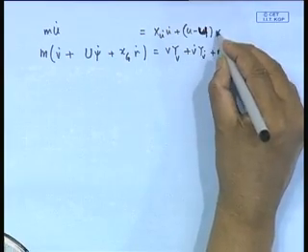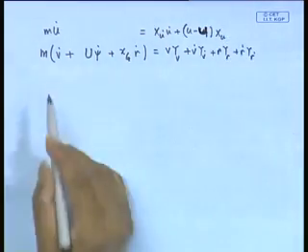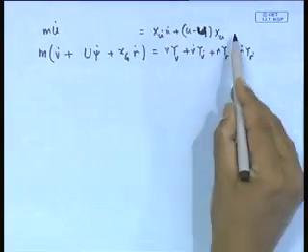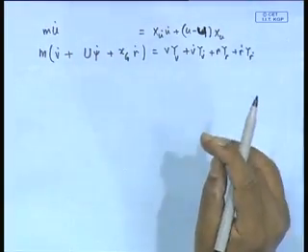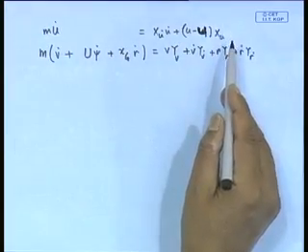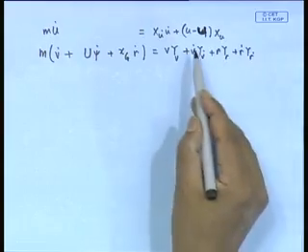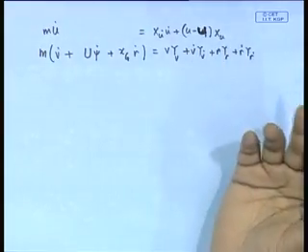What I mean, in the x equation, the other terms, variation of x against v etc., can be neglected, because the x force in the x direction would not depend on the v and y motion so strongly. Therefore, we can ignore that. So, this in fact becomes your surge equation in a steady state case, because this becomes my resistance, essentially x u etc. So, we can still write that way.